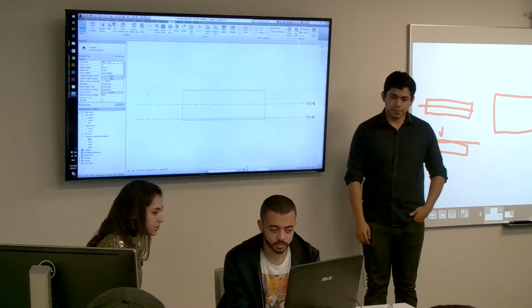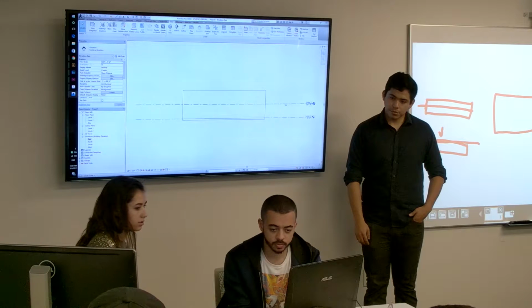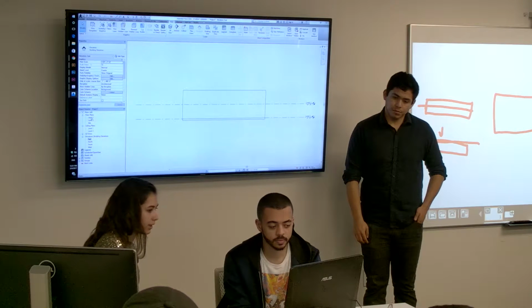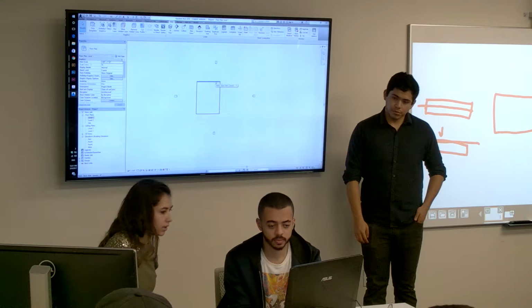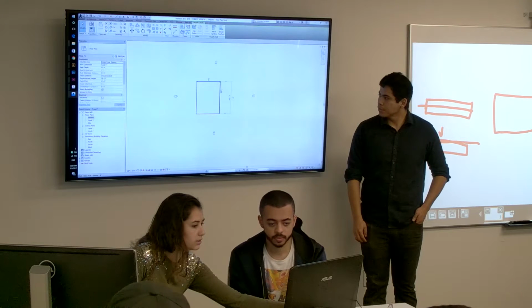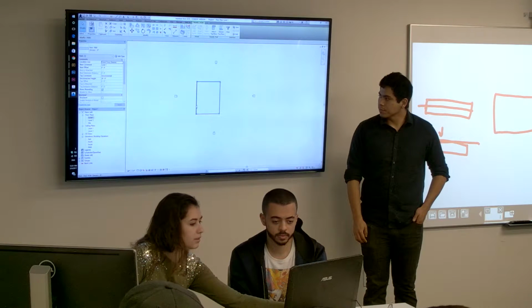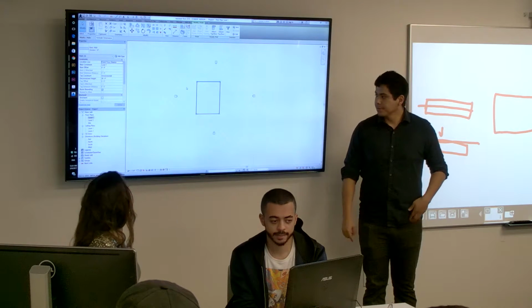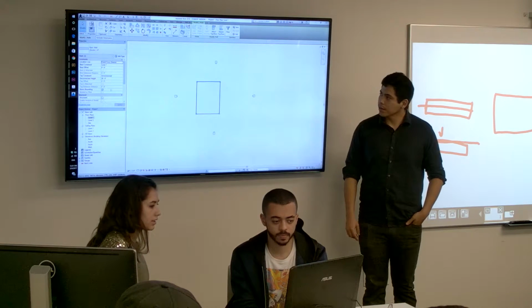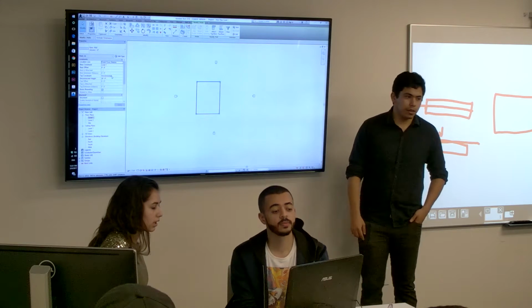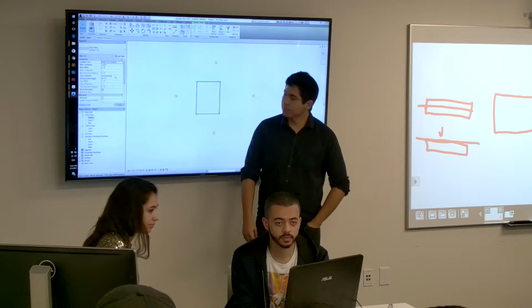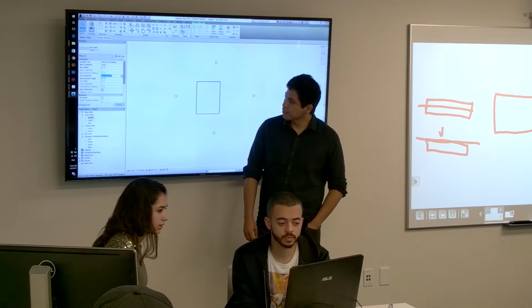So what we're going to do is change our wall height down to our level 2. We're going to go back to floor plans, level 1, and hit control and select all the walls that we have here. You hit control, not shift, control. And then, hopefully you have the properties on this side, otherwise just right click and go to properties. So we're going to go to unconnected, change that to level 2, and hit apply.